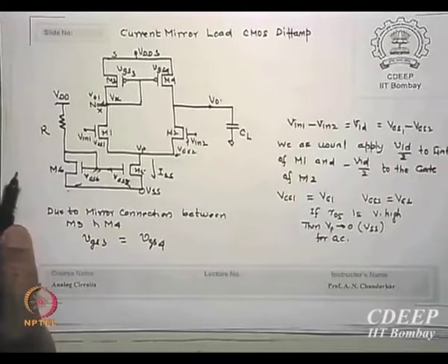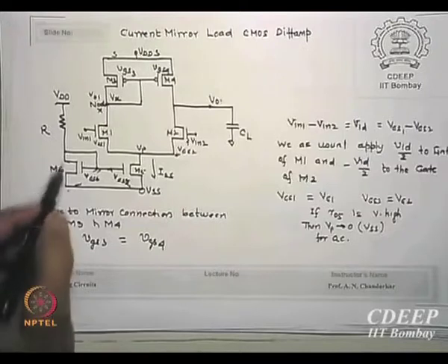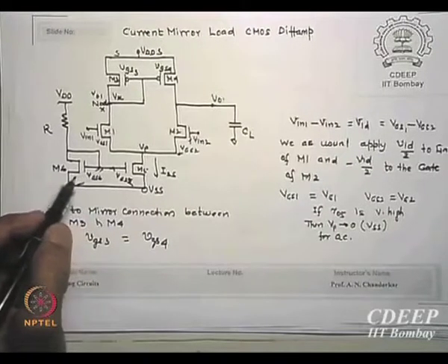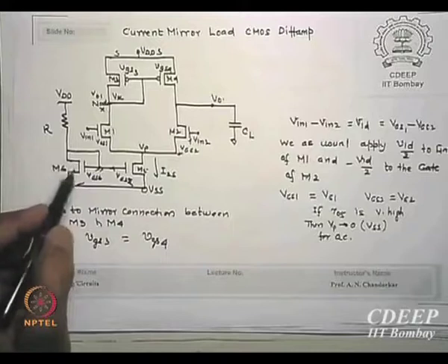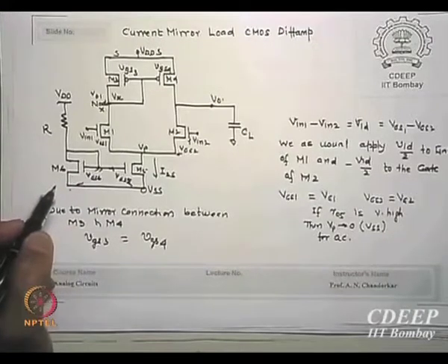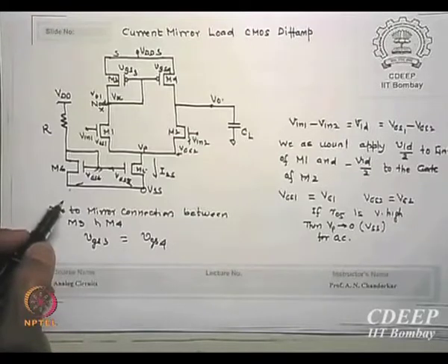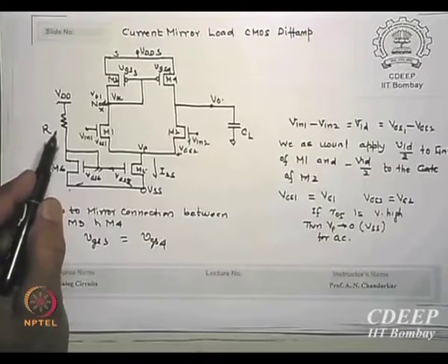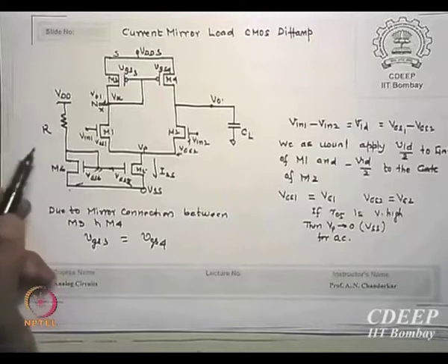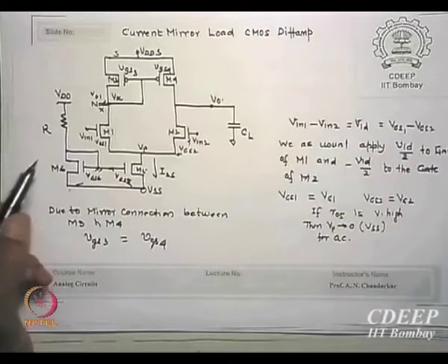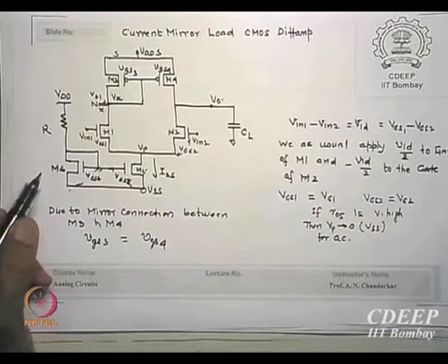That is what I did now. When I calculate the current and assume this transistor in saturation, I am forcing the value of resistance such that the transistor remains in saturation with that kind of VSS available. If it is ground, this value will change, is that correct? If minus VSS, it will change differently, okay, but it will force both transistors to be in saturation.